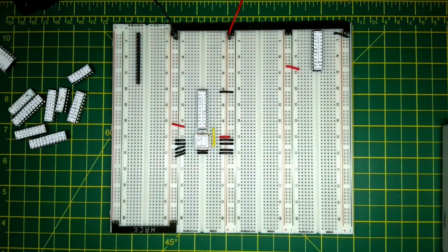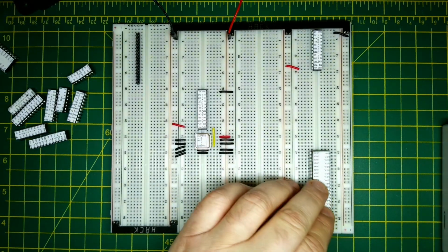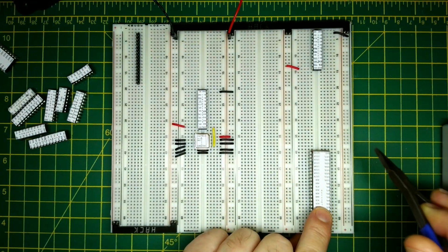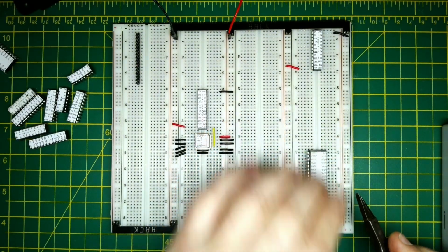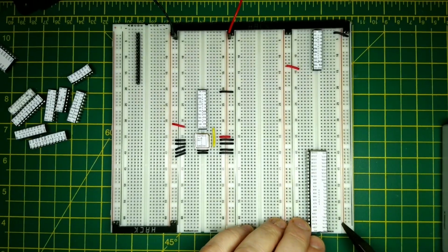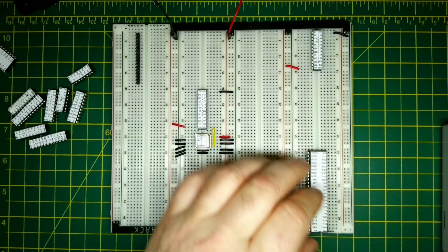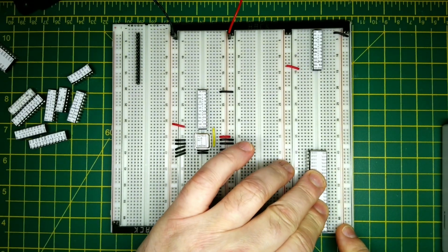So we're just going to put all the chips in. This is the video RAM, and it's just going to squeeze in here. A lot of the lines from the buses are going to come in on this side, and then we're going to feed them over to other parts. So we're going to need to leave slightly more holes on that side, I think, for the moment.